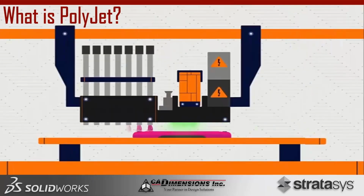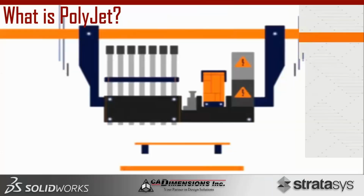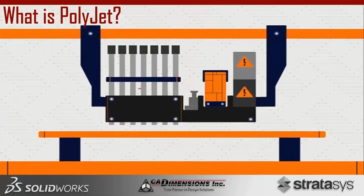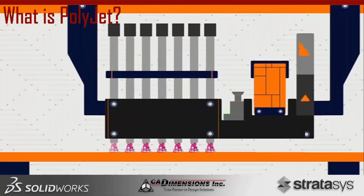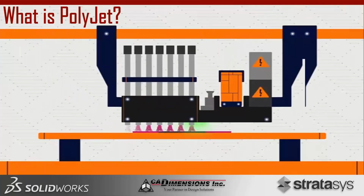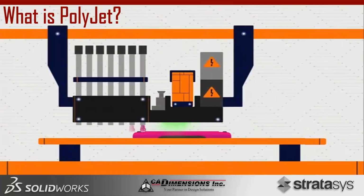So all you have to do after that is remove support. Now we have soluble support for PolyJet, so you can now just throw it in a tank and walk away. And then do any post-processing you see fit, anything like sanding, painting, although painting might not really be necessary with the newer technologies because of the high color spectrum that we boast.